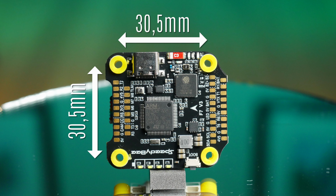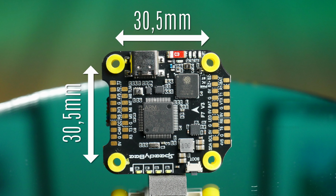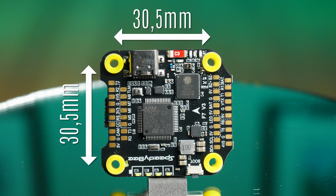In case of the multirotor flight controllers, there are currently 3 most popular form factors, and they are described by the distance between the mounting holes and the orientation of the flight controller. The big standard flight controllers are the ones with the 30.5 by 30.5 millimeter hole spacing.